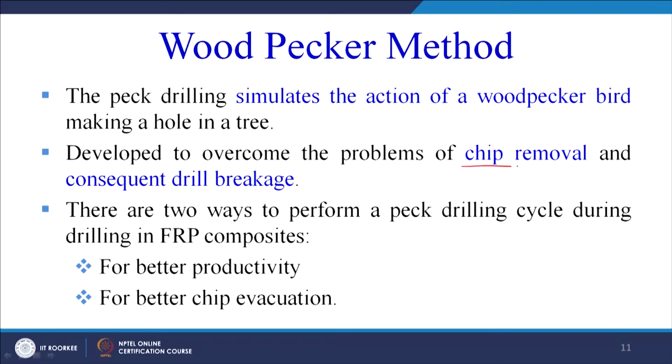So peck drilling is a similar action, developed to overcome the problems of chip removal. If you do it step by step, chips can be easily evacuated, and consequently drill damage, or drill breakage, is also minimized. There are two ways to perform a peck drilling cycle during the drilling in FRP composites. FRP is another name for polymer matrix composites. So why do we do peck drilling? For better productivity, for better chip evacuation.